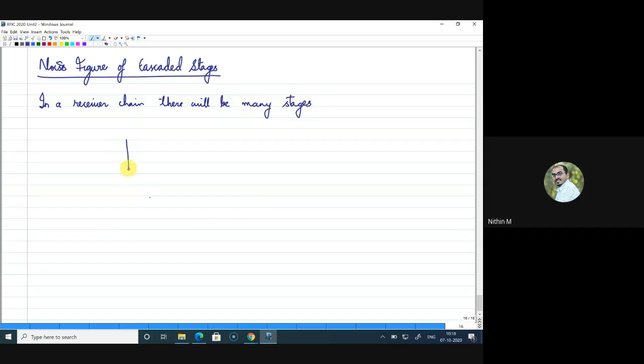So I'm considering 2 gain stages. One is this. So this stage, from input to output, is providing a gain of say AV1. Now, as I mentioned before, the stage is represented as a noiseless stage, but the noise of this stage is represented as the output noise here, and we mark it as Vn1 square bar. This is for the first stage.